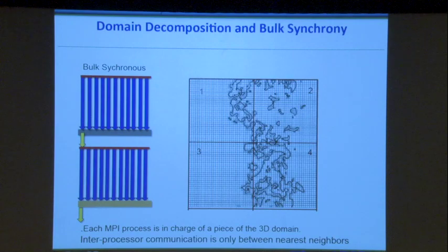Typically, most of our CFD codes are written to be sequential, and they're bulk synchronous, meaning that you do a bunch of computations, as shown in this top left block here, and then you wait for the slowest member of those various processors to finish. This is what they call MPI wait. And when that happens, then you move on to the next computation.